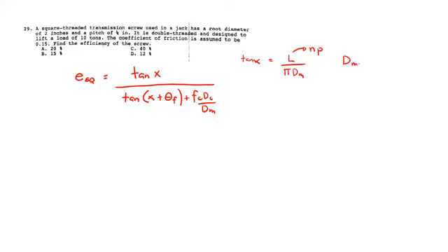The mean diameter is equal to Di plus h, where the h we use is 7 over 16 times the pitch for square threads. So the mean diameter is equal to the inside diameter, which is the root diameter of 2 inches, plus 7 over 16 times the pitch of 1/4. That gives 2.1094.